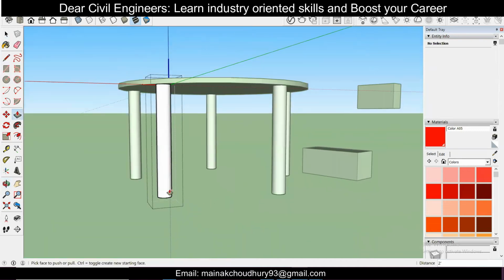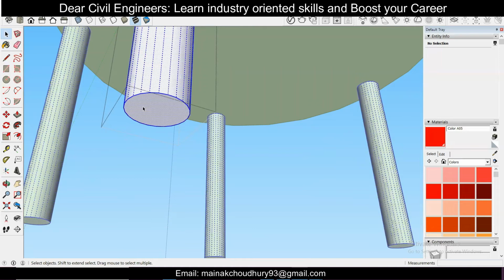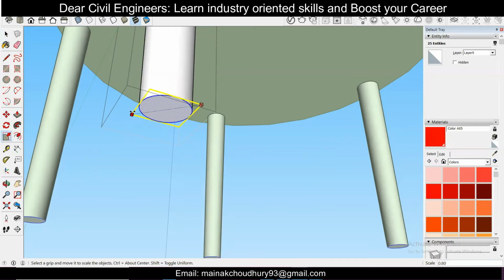Now since this is in a group, you can easily use the scale option. Before using the scale option, use the select button and double click on the face. Just double click and then double click on the face. Just the face is selected. We want to give it a particular design. So use the scale tool and give this a design.